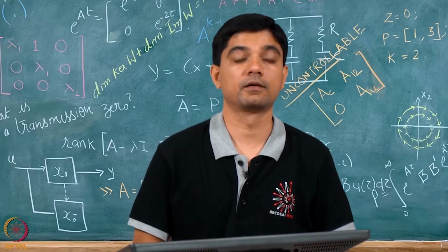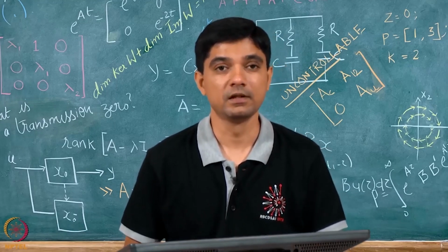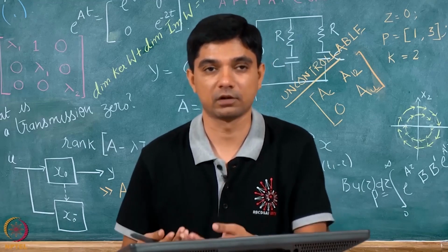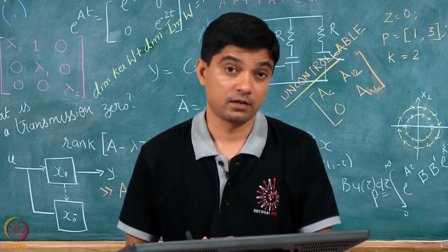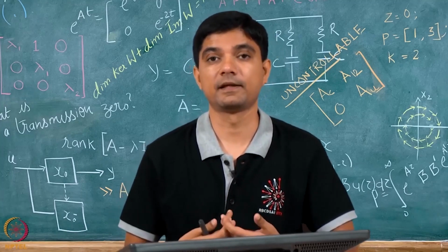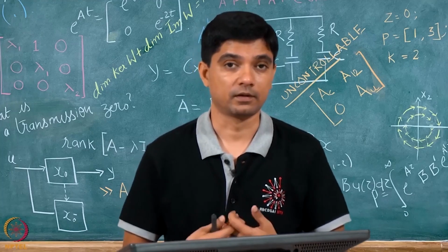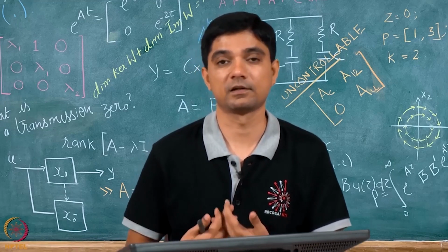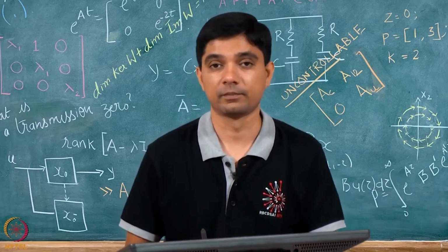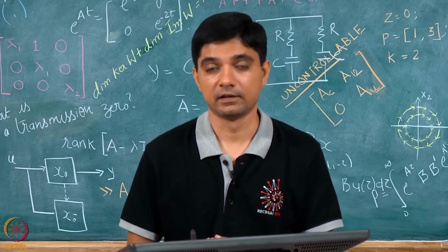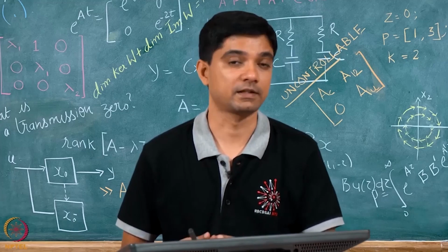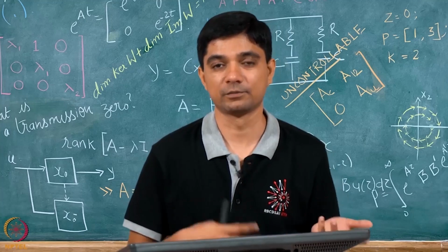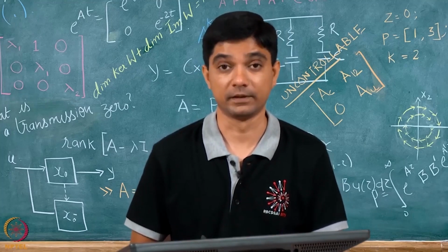All the time, computing eigenvalues may be computationally expensive, even though I am doing it on a computer, say via MATLAB for example. For a large size matrix, it might take me a very long time. Now, are there other or better kinds of conditions that I can check which are computationally efficient for me to verify if the system is asymptotically stable or not? I will just use one word, either asymptotically stable or exponentially stable, and they would mean the same.